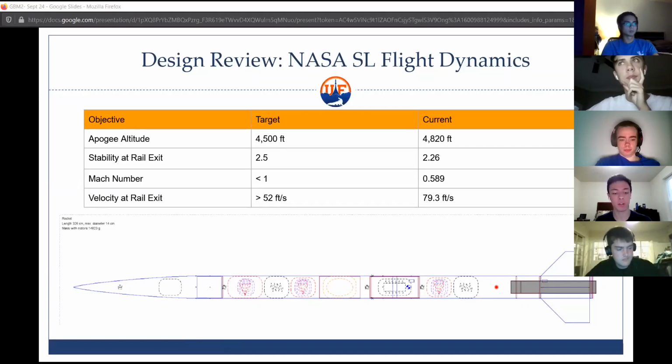So those are all put in based on what the structure of the rocket is going to be like. They don't look exactly like what those components are going to be like, but it's more symbolic. So we have their weights, we have their positions, as well as their size, so there's no interference. And we can place them along the rocket. So when we run the simulation, it takes into account those weights, where the weights are distributed, things like that. So when we run the simulations, we can get a couple different important parameters, which is what we've been doing. And we basically need to match those up with some of the requirements that NASA gave us in the handbook and make sure we're satisfying the requirements.